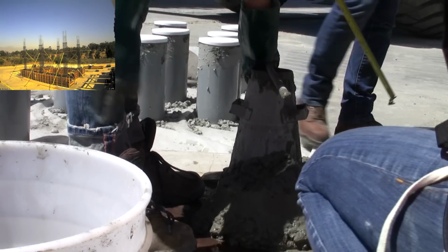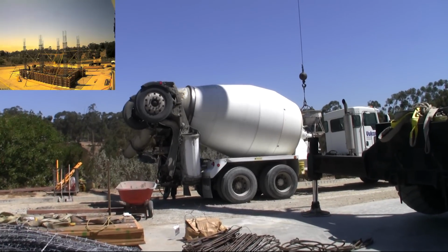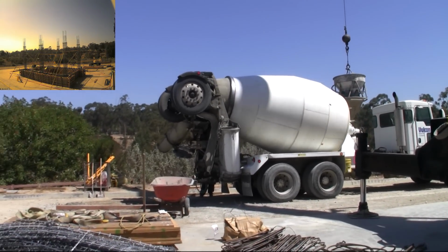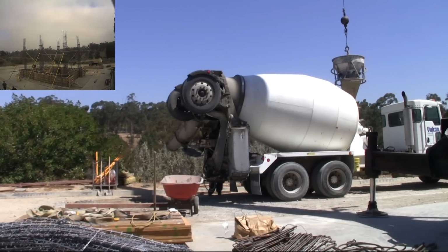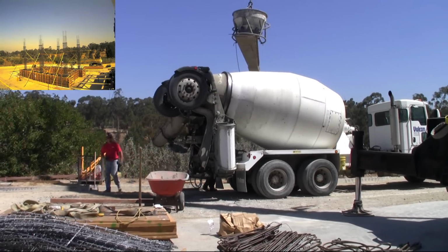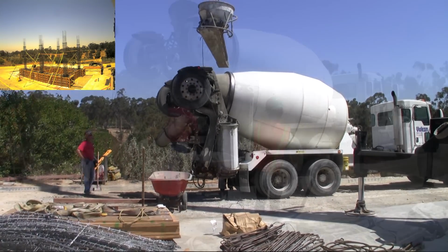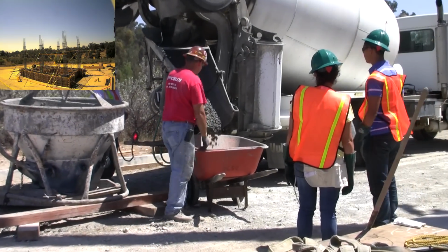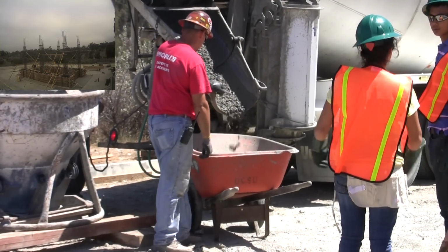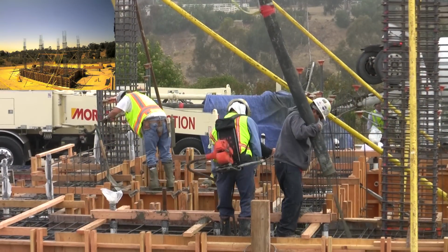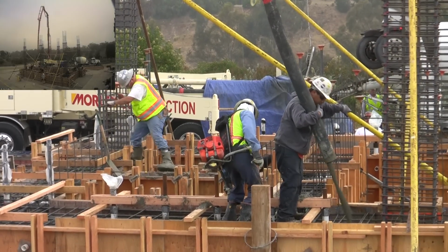The concrete mix is primarily composed of cement, water, and coarse and fine aggregates. Cement is the mix binder and hardens in the presence of water. The ratio by weight of cement to water is an important indicator of the strength and workability of the mix, and typically ranges from 40 to 60%. The aggregates are small and are usually made up of materials such as sand, gravel, or crushed stone. The aggregates are used to reduce the final cost of the concrete as well as provide volume stability to the hardened concrete. In this project, the concrete was poured using a truck-mounted boom pump method.